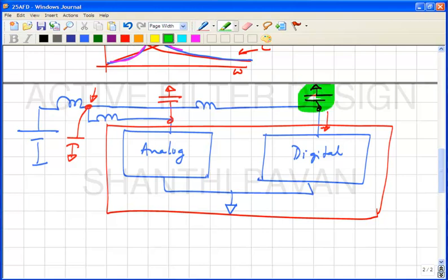It all goes through this capacitor, because that's got the lowest impedance at high frequency. A very small portion of it will go here, and most of that will go through this capacitor, correct. So, this voltage drop at high frequency will be even smaller. Now, that is getting filtered through this LC network, and the voltage drop across this capacitor is even smaller. You understand?